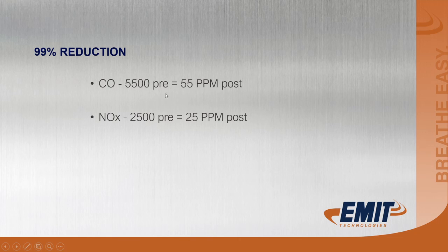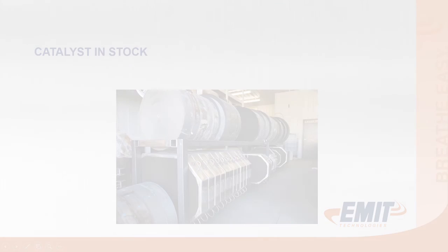99% reduction, that's closer to a new catalyst element, where everything's brand new, engine's running perfect. 5500 in would be 55 ppm coming out. So we're 1/6 of where we need to be for 1 gram permits here. So it's a great reduction, great opportunity.